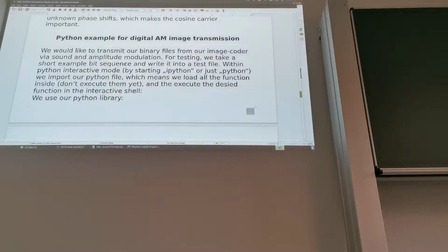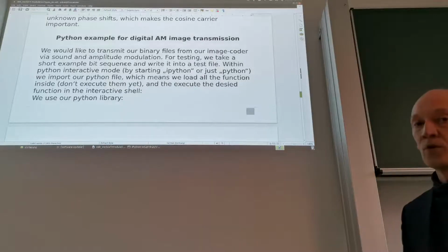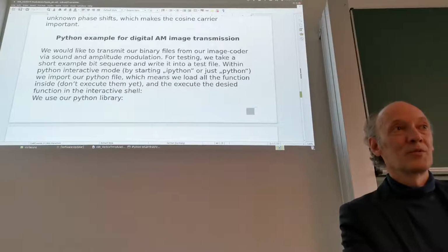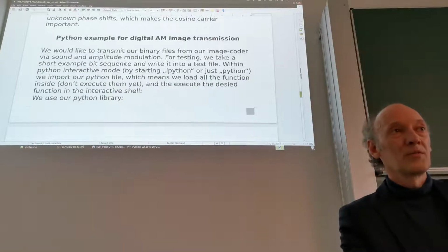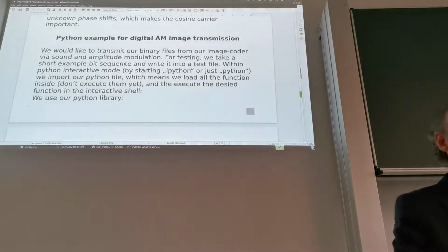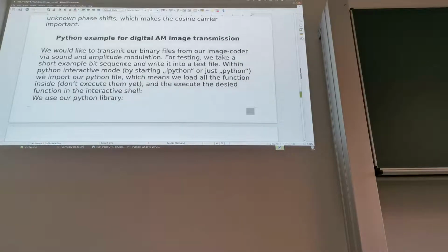And first we need to distinguish the 1 from the 0. Right? And we need to give the 1 and the 0 different signal shapes so that the decoder can distinguish between a 0 and a 1. Right? And the simplest way would be to give the 1 a high value and the 0 a 0 value. Right? So if you have a tone, then this is the 1. If you have no tone, that's the 0. That's the simplest. It's usually not the best, but it's the simplest.